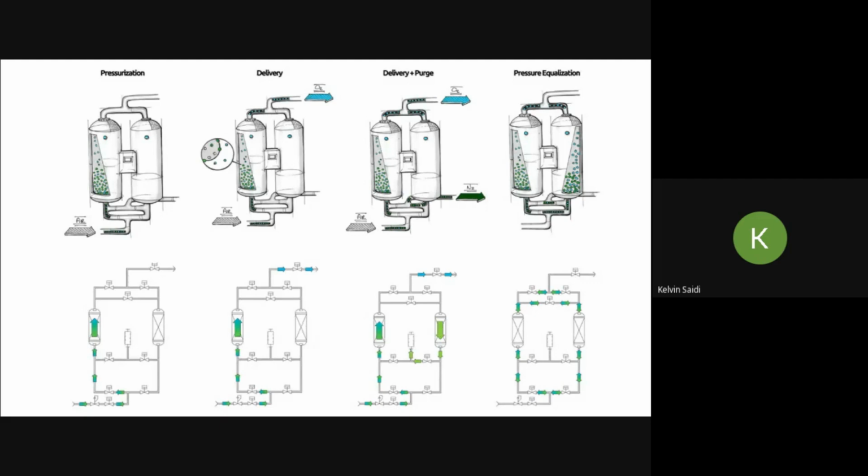The first purpose is to equalize the pressures in the sieve beds so that the bed that was just depressurized does not start at zero pressure for the PSA process, pressure swing adsorption. The second reason is to remove excess nitrogen from the sieve bed for the production of higher oxygen purity.